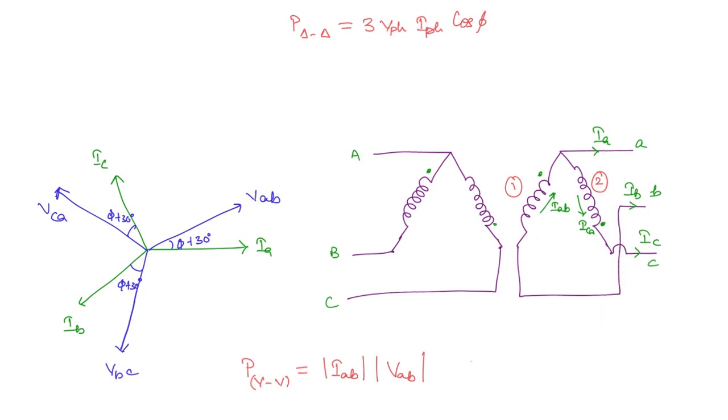So you can represent this in the phasor diagram. This is going to be minus IB, which is IAB. Now what is the phase between this voltage VAB and IAB? So this angle is 180 degrees, this is 120. So what is this angle? It is going to be 60. Now this angle is phi plus 30. So what is this left out angle? This is going to be 30 minus phi. So here you have cos of 30 minus phi.